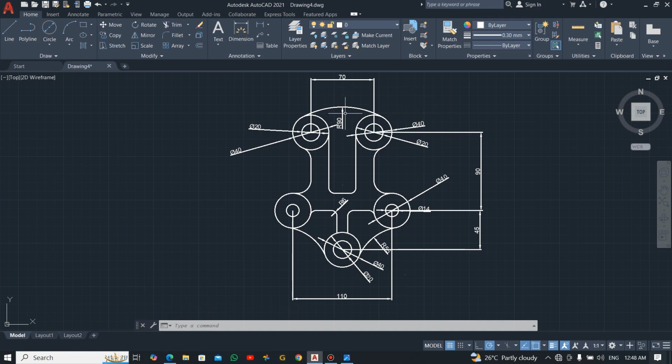But you can see the dimension lines are all together with the drawing, having the same line thickness, and we don't want that. So if you don't want that, you can select all the dimensions that you did, and reduce the line width for that one. Only the dimensions. Good.